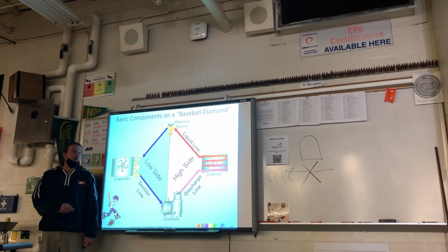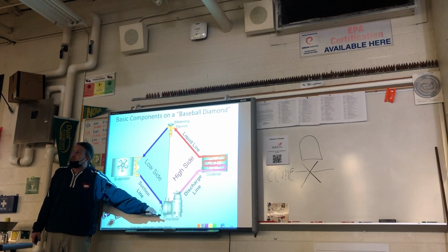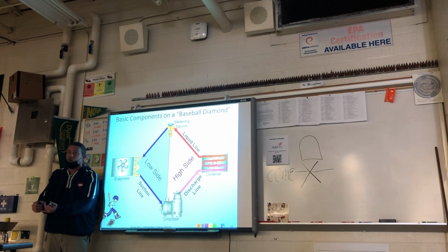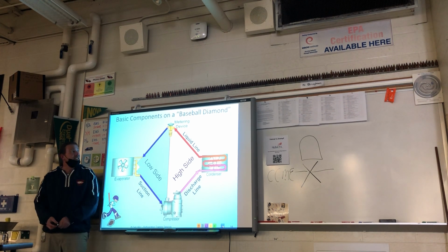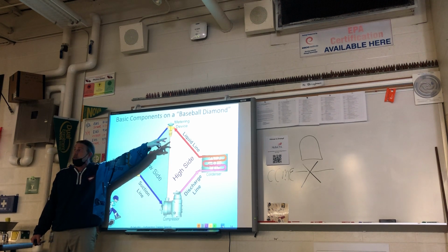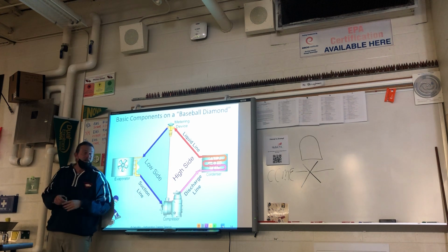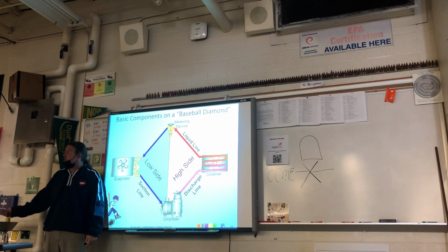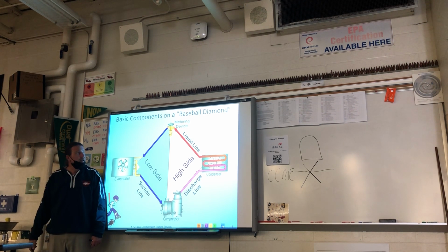I do want to talk more with you about the different components. Now I can break it down to where there's six different types of compressors. There's a screw, there's a rotary, there's a scroll, there's a reciprocating, there's a centrifugal. There's six different types of metering devices. There's the floats, go on the high and the low side. You showed the electronic one. We talked about the cap tube already, the piston, and this one here is what? What do we call this one? A TXV. Very good. That's right.